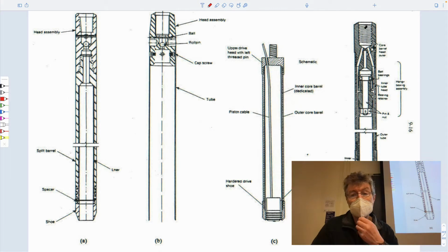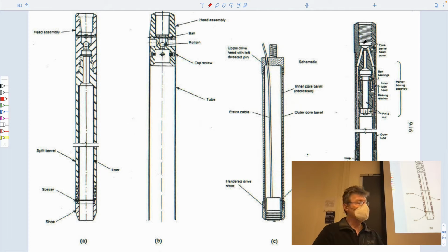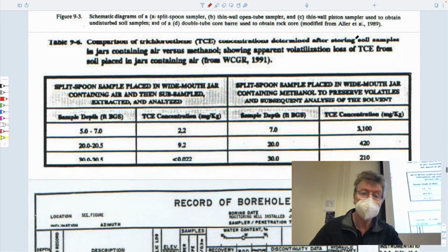So one of the biggest costs in drilling, if you look at, for instance, deep geothermal wells, the biggest technology change that's needed is this: when you go down 4 kilometers and drill a well, if you're just using a tricone bit in really hard rock like granite, the bit won't last a single hole. You might use 20 bits to get down to 4 kilometers. As soon as your bit wears out, you have to drag all the drill string up to the top, replace the bit, and then re-trip back down to it. So the big cost in terms of time is actually pulling the stuff up the hole and then re-entering it down the hole, etc.